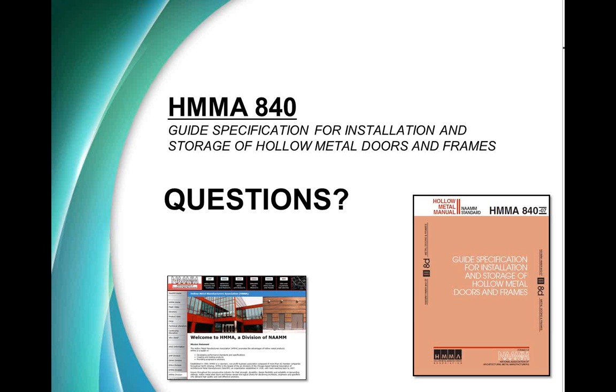It does provide a high probability of rusting out the frames, and in many of the existing masonry anchors, they do not allow for the flow of the mortar through the anchors from the top of the frame down. There are some contractors that will mortar the jambs before they install it in the wall, but it's really not recommended. I don't think there's any manufacturer that does recommend that. It just creates problems and opens up distribution and manufacturers to back charges.